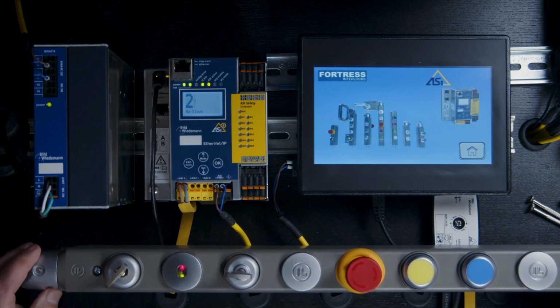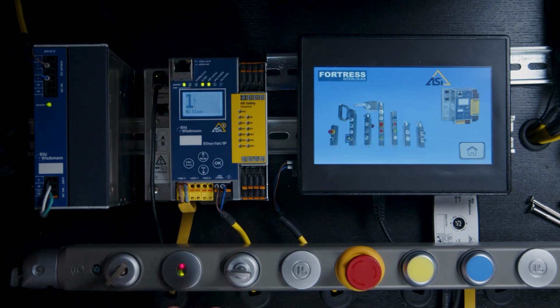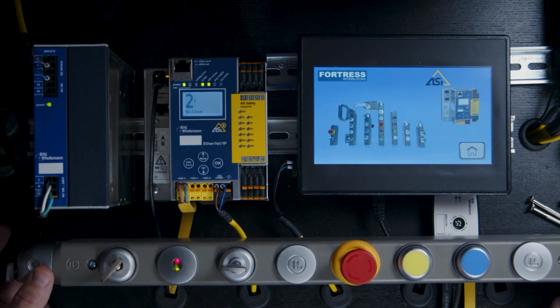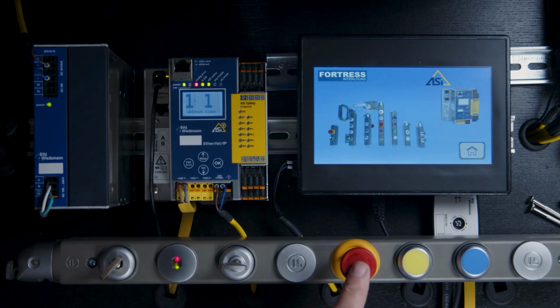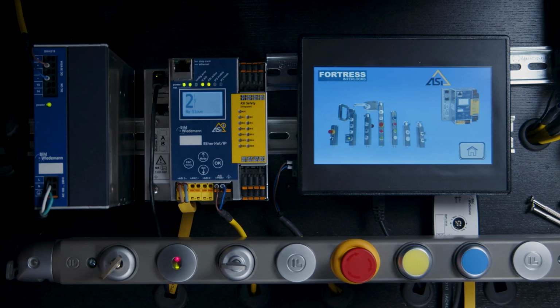Okay. Now let's take a look at what we have here from an ASi standpoint. So physically, we've talked about how to physically connect it, but in terms of the ASi addresses or ASi functionality we have here, we actually have 4 different ASi addresses built into the tGard. So it has 2 safety circuits, okay? It's got the door switch safety circuit. It's got an e-stop safety circuit. And those are addressed at 0 and 1 on the ASi network by default. And then it has some push buttons and some status indication that are just standard I/O. And those by default are addresses 2A and 3A.